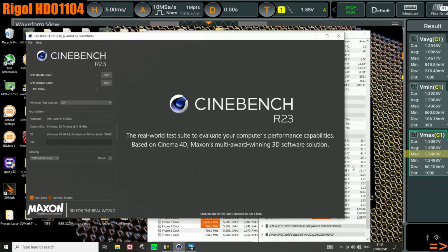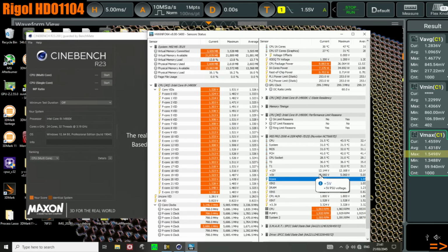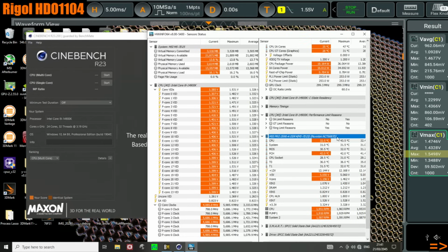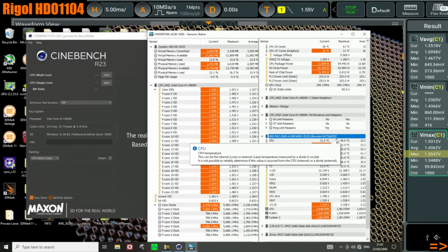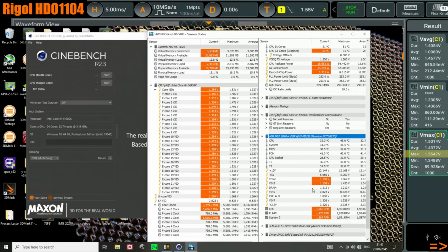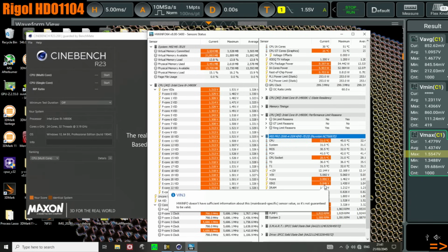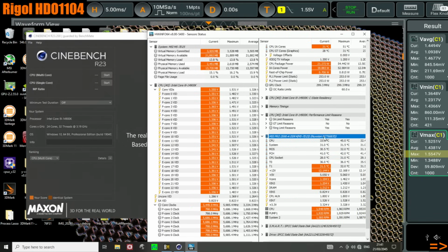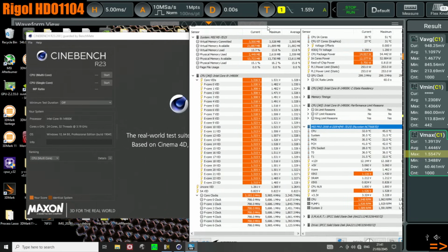We're not going to go into how to prove that right now. It's just a quirk of how the sensors are wired on most Intel motherboards, actually. Basically, the voltage readings from the Nuvoton chips are never accurate. Okay, that's not true. There are some motherboards that have a pretty fancy workaround for this issue, but generally speaking, the voltage readouts from the Nuvoton chips aren't accurate. You need to verify that they're actually accurate, and we're not gonna get into how to do that today.